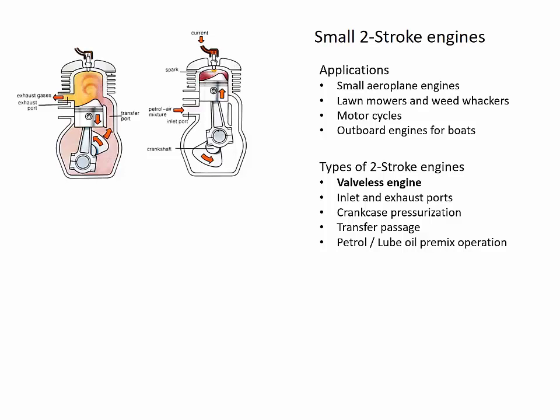So the picture demonstrates an engine that uses what we would call crankcase pressurization as a way of supercharging the engine. There is no suction stroke or exhaust stroke as such, so the air has to be forced into the engine. In this particular instance, as the piston moves upwards inside the engine, the crankcase space becomes larger and creates a suction which will draw in a petrol and oil air mixture into the crankcase space. And then when the piston moves downwards, it compresses the space. The crankcase space gets smaller.